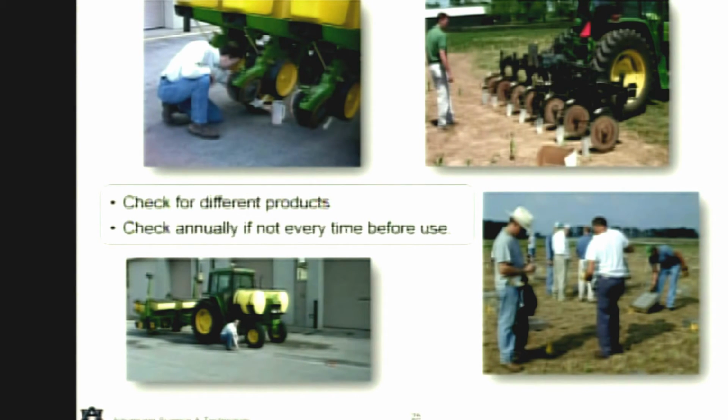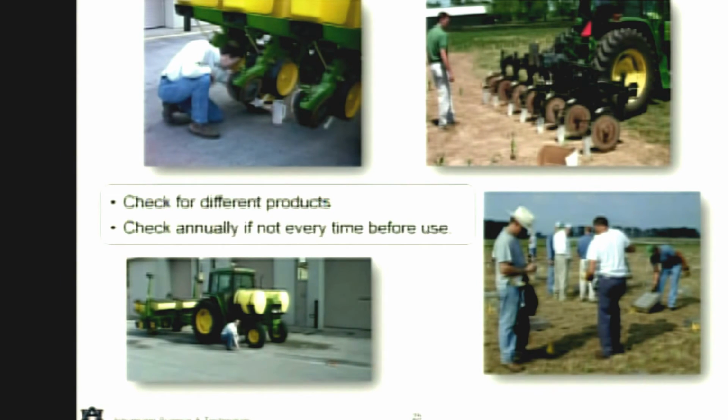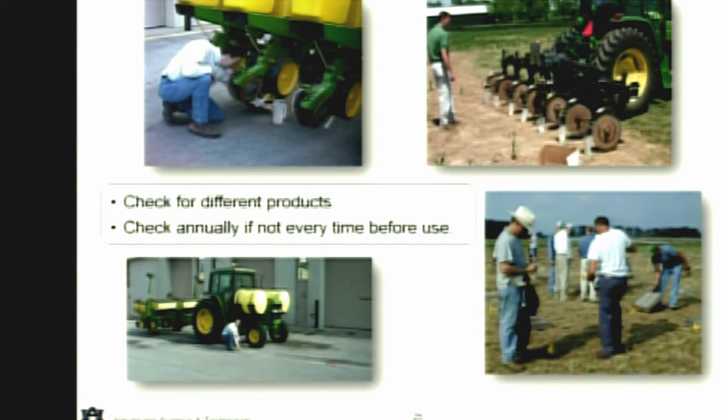You can very quickly get your planter really fine-tuned into that target rate. Same with the nitrogen applicator. And then in the bottom right, we always encourage people to really fine-tune their fertilizer spreaders. We can basically weigh that material coming off the apron chain to make sure that what the computer thinks it's doing is actually what it's doing, and we can get that down to 2 to 1% or less error, which is really where we want to be, not 5 or 10% that we'll get a lot of times with some of these manual-driven